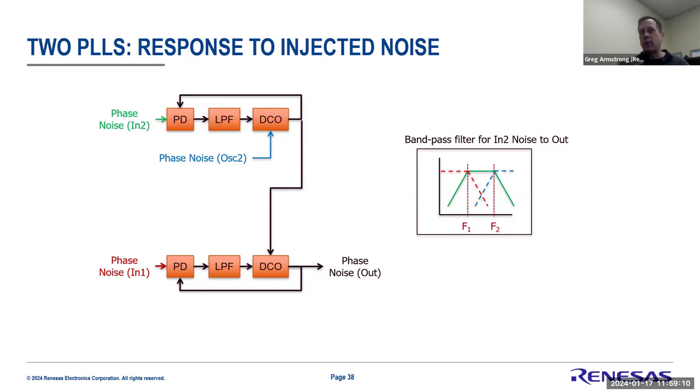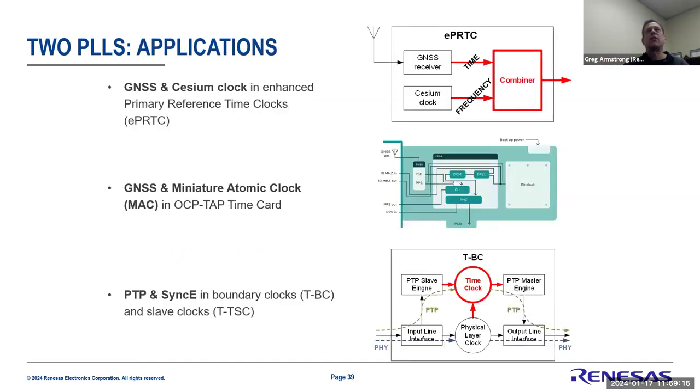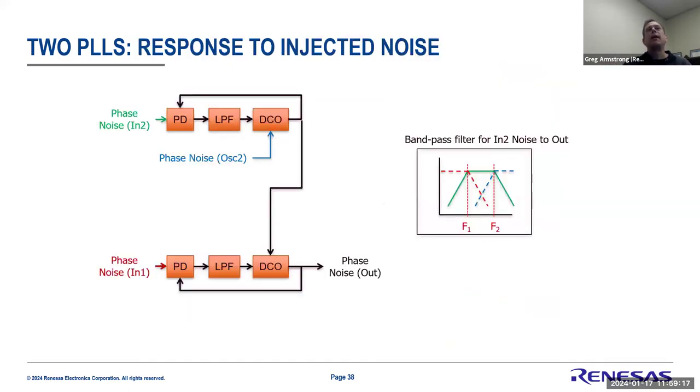So I can take characteristics of, let's say, a physical layer synchronization clock, which allows it to run at bandwidths that are much higher because it's working with much higher frequencies. It can basically filter things out and react faster to it. But I could feed that into something that maybe is running a little bit slower because it's packet based. It's only getting 16 updates per second, or even 1 packet per second. And I could combine that to try to get an overall combined clock that is very stable, right? Much more stable than a local oscillator because it's now traceable to a cesium or rubidium clock, but I also still get my traceability to the time source.